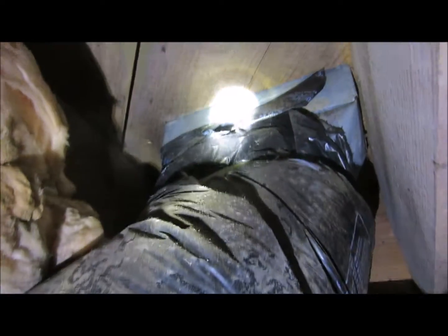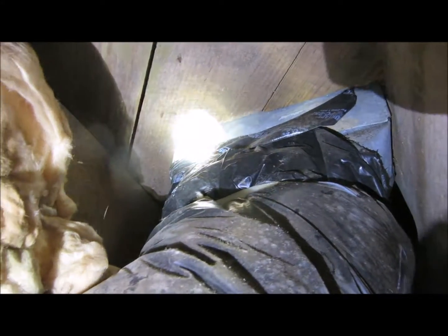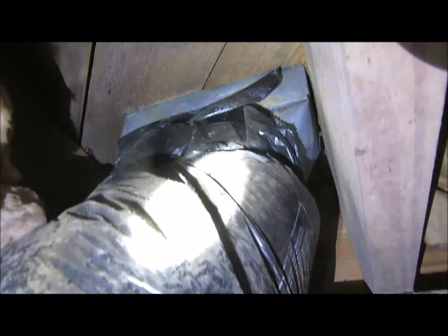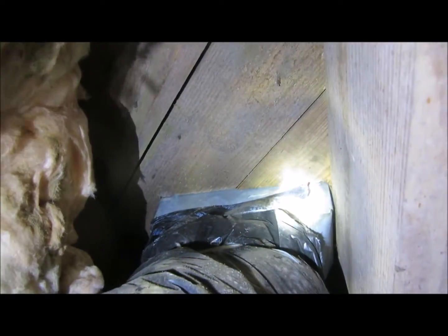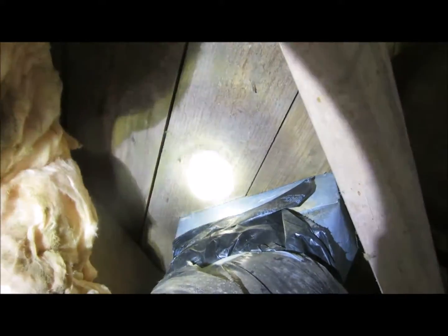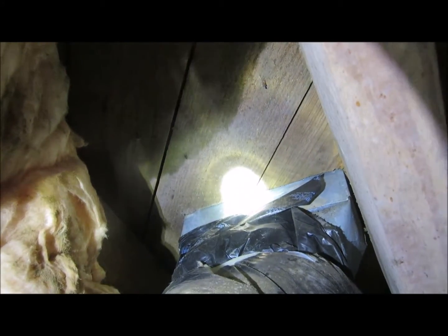Here is a supply duct which has extensive mold growth on it, and then the signs of insects that have been harvesting the mold. And then we have a boot that is unsealed, so the mold can go right into the home. There's even a little mold growth up on the subfloor. That's probably happening because this insulation is in backwards, allowing moisture to be trapped up on the subfloor. So these ducts should be cleaned of mold and the boots sealed.